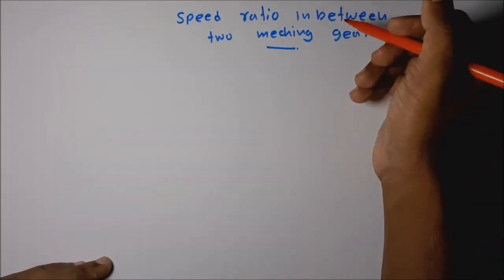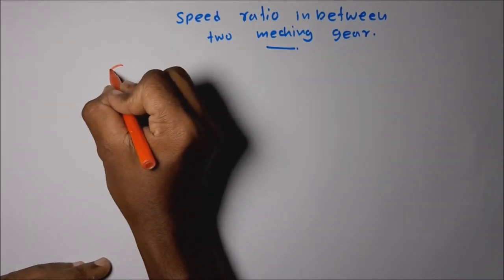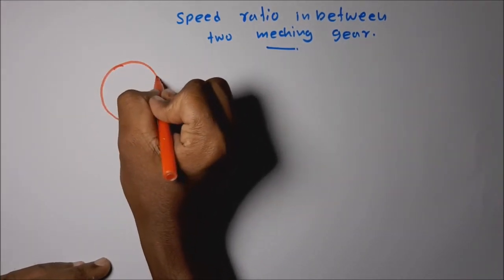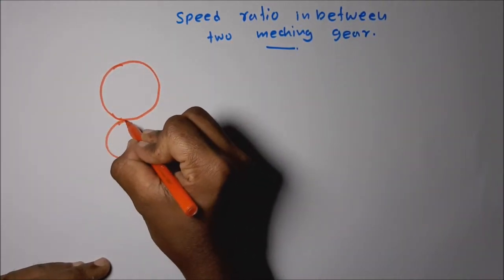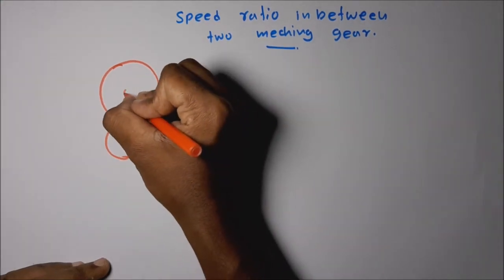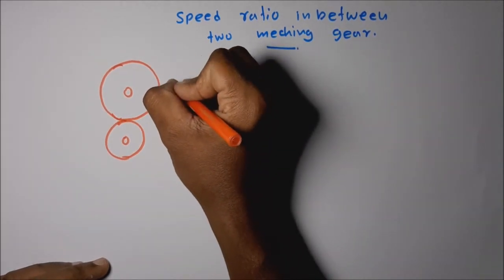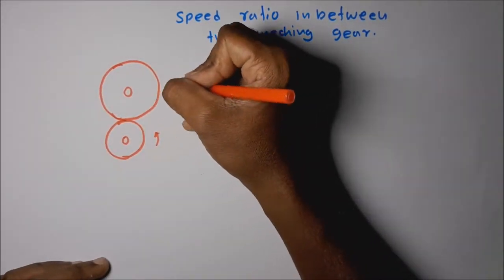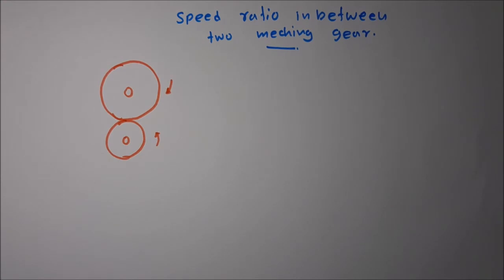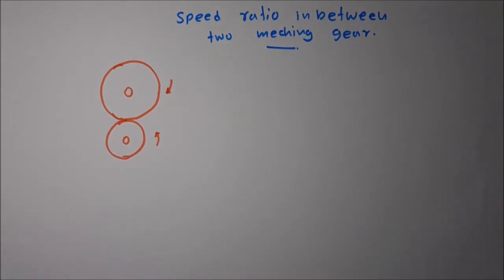Forget about the gear wheels. Let's take friction rollers, this kind of friction rollers. This is the roller. Let's take another roller contacting this larger diameter roller. These two rollers are in contact. This is rotating and this is also rotating without slip. These are friction rollers with cylindrical surfaces, rotating without slipping.